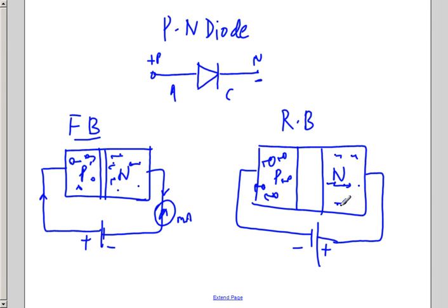This makes the depletion layer, in the sense the layer which doesn't have any mobile charge carriers, neither plus nor minus. So in the case of reverse bias, this depletion layer will increase, but because of the minority charge carriers present in p-type and n-type, there will be a small amount of current still flowing in the circuit, which can be measured by a microammeter.